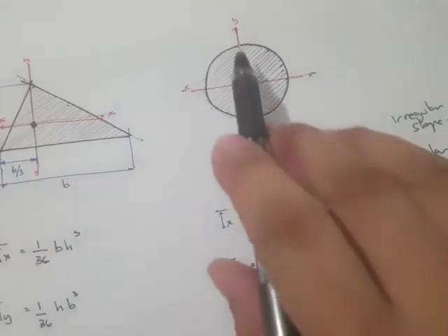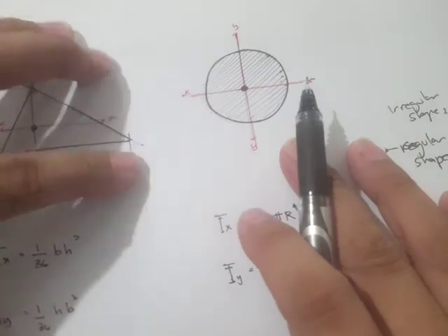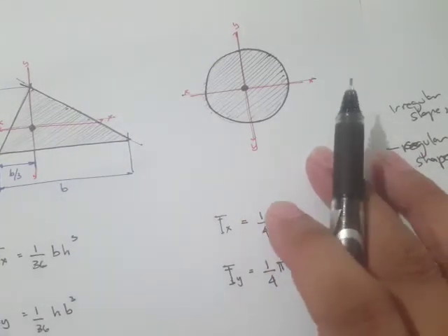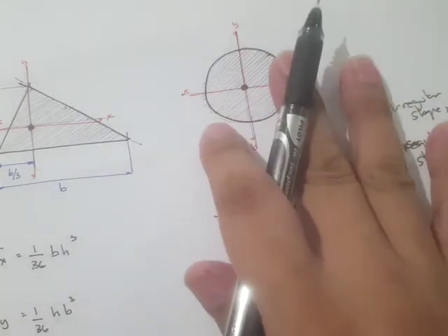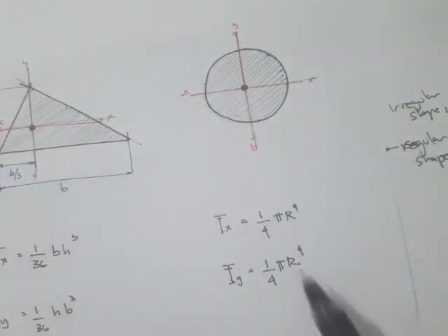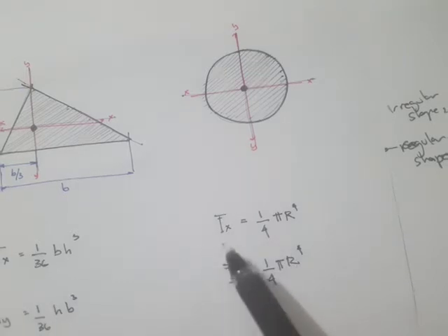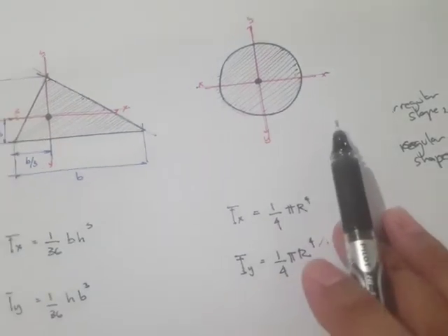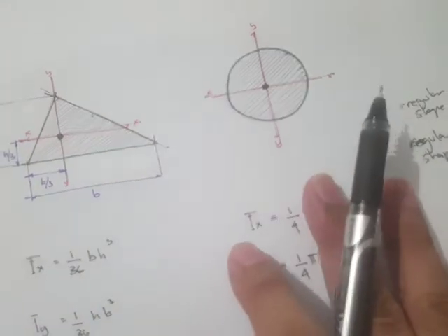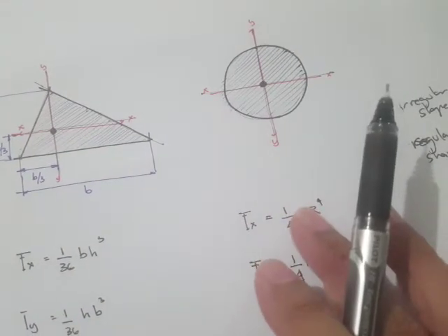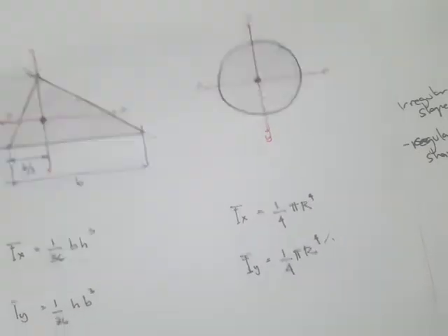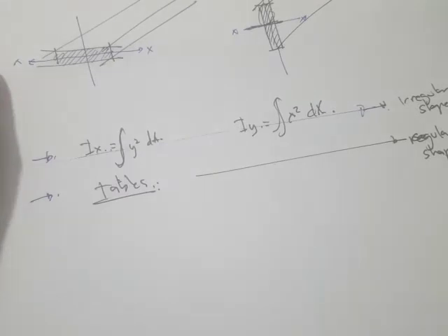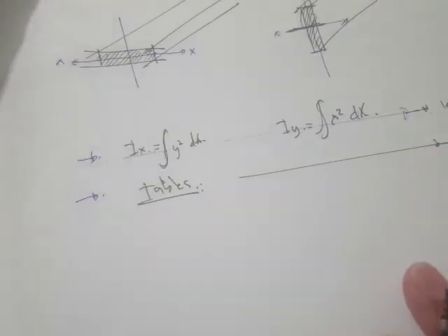Since this is not just symmetrical but rather a doubly symmetrical shape, meaning that in either the x or y direction it's the same, the moment of inertia along x and along y are the same. And there are still many other shapes; you can find the equations for them in the references or textbooks, but that's the main idea.